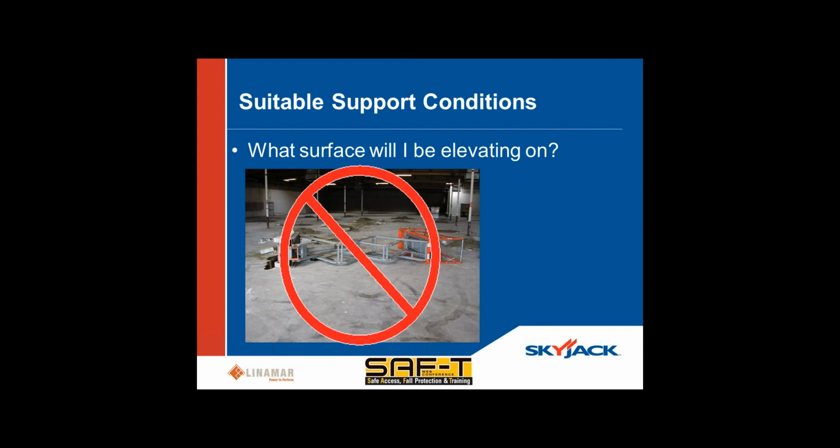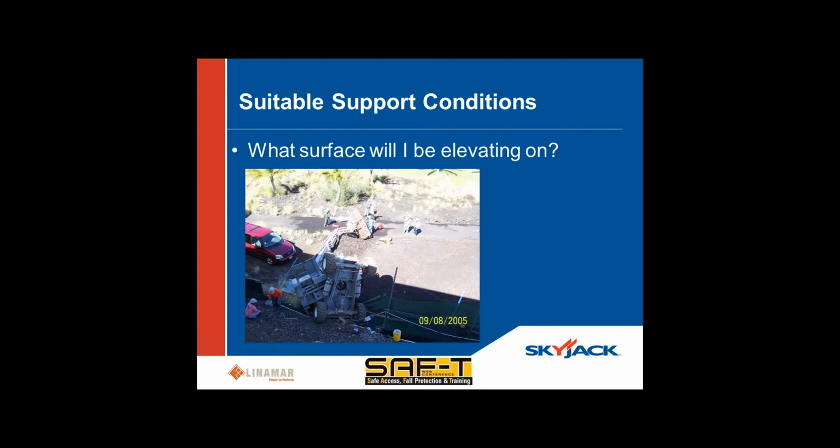And so that's not an appropriate surface for that type of machine, and there are other precautions you should take in that case to ensure that you have a firm level surface that doesn't have holes in it for that particular machine. Or if it does have holes in it, you have to have some sort of control plan to ensure that you're not going to drive your aerial lift into those holes.